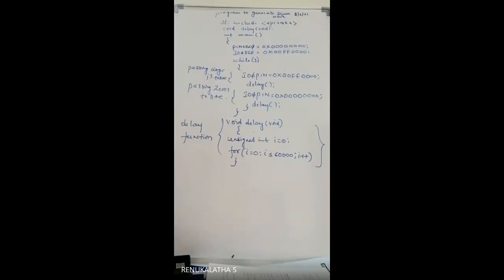So how does the microcontroller send the data? Through the register. First I have to place the value into a register, and whatever value you place in the register will be placed as data on the corresponding port. Then the port will be connected to the DAC. The data is available at the pins, depending on the direction and everything being made ready. Whatever data is placed on this register will reach the DAC.